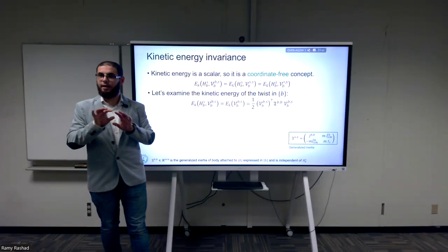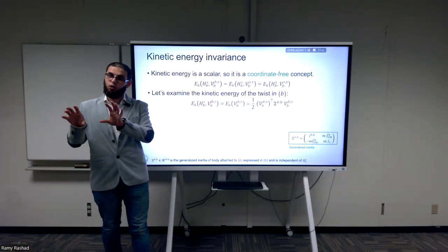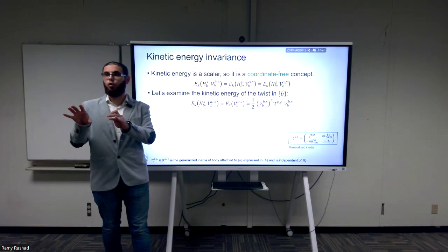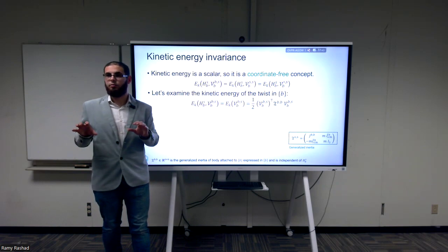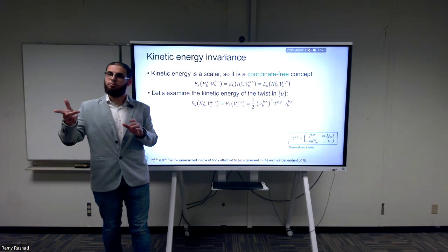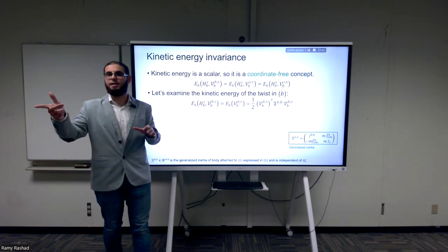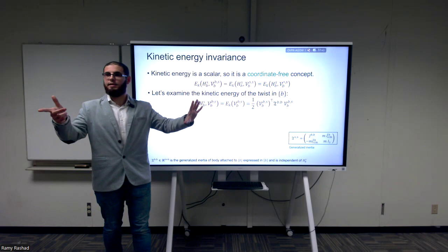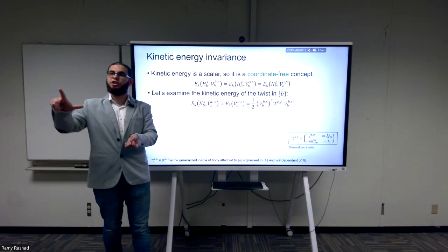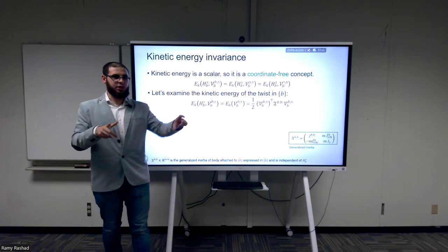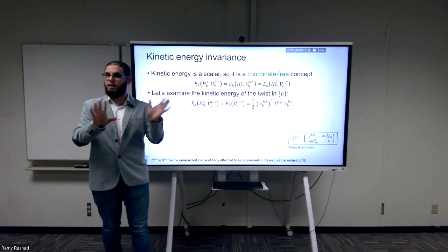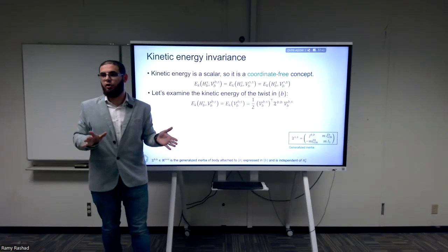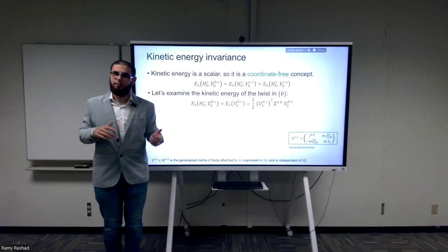That is true. But again, simply you can say that if you want to check whether 2 quantities belong in the same space, they have to change coordinates differently. That's the key word. Okay? So if you have a twist and I give you something that's new, right, a 6-dimensional number, and I tell you change the coordinates of the twist, how does it look like, and change the coordinates of this new 6-tuple, and if they change with the adjoint matrix, they are both vectors. If not, they are not the same. You need to introduce a new space. Okay?